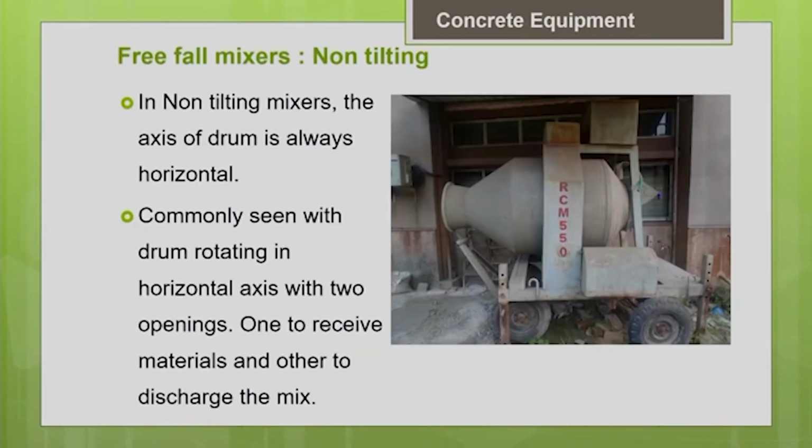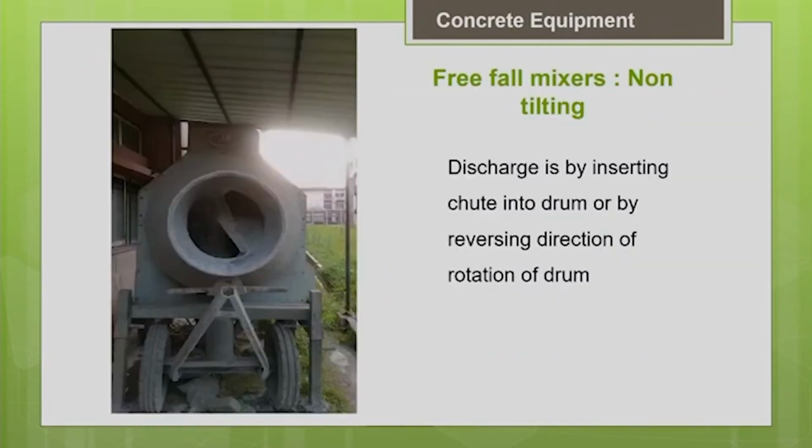The next is about the free fall mixers, non-tilting type. Here I cannot change the angle of inclination of the drum. You can see that the axis of the drum is always horizontal. And commonly you can see this with two openings, one for feeding in the material and one for discharging the concrete out. This is a common configuration you can see for the non-tilting type.